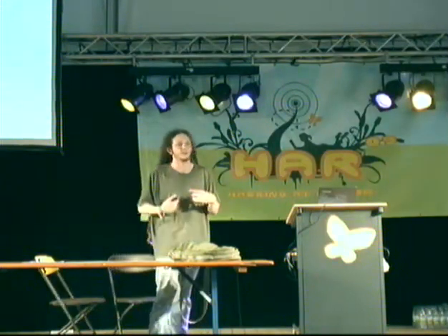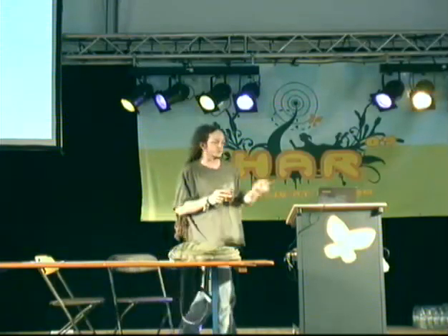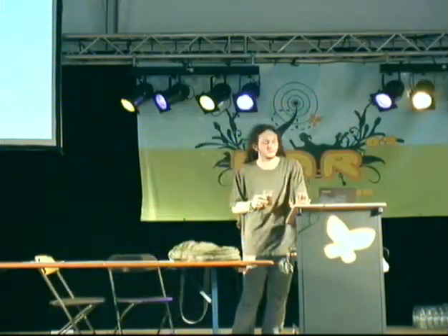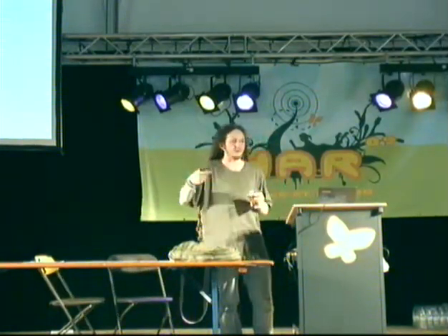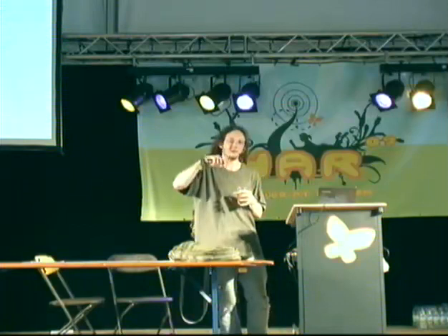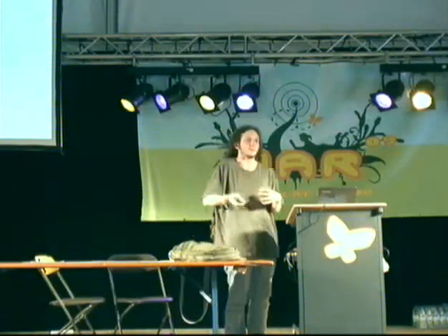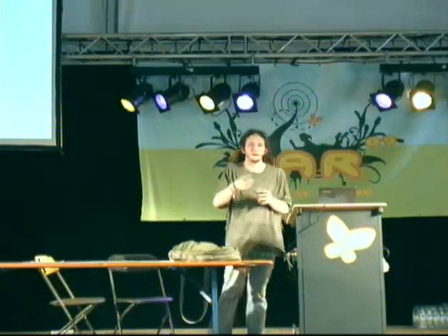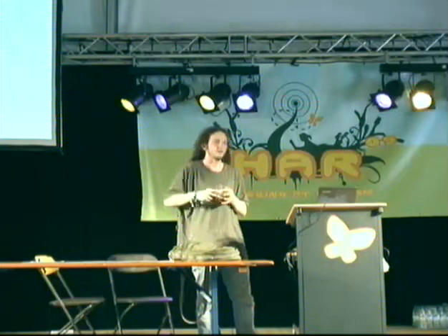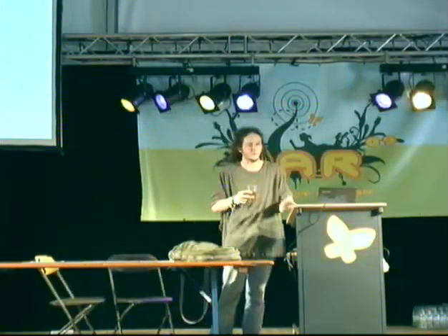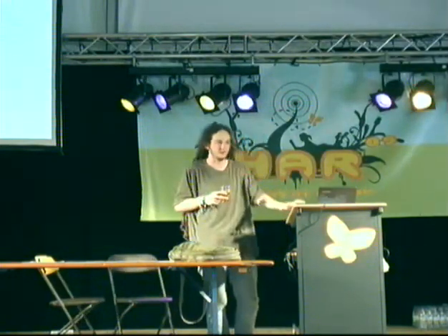It then looks at its memory and sees that you're not allowed to have access. So the state machine runs from three states. It begins in a wake-up state where it fetches this value from memory. Then it proceeds into a fuse check state where it looks at this value and decides whether or not you're allowed entry. And then it goes to a third state, which locks you out. So you have two state transitions. You have one from the initial to the check, and another from the check to the deny state.